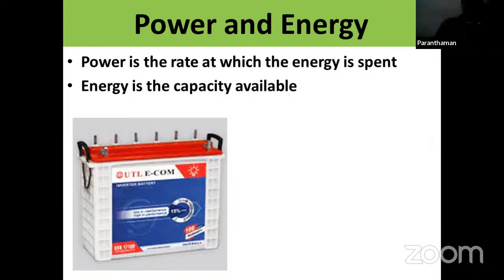Ah means ampere and current. 100 Ah means it can deliver when connected to a 12 volt load 100 amps for 1 hour, or 50 amps for 2 hours, or 10 amps for 10 hours. The product should be 100. The maximum power it can deliver is 100 Ah with a terminal voltage of 12.